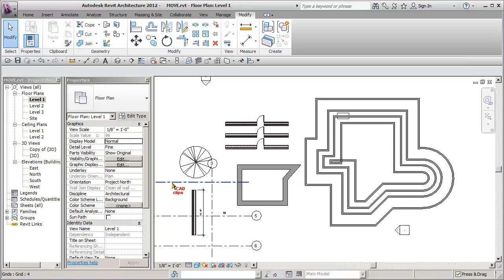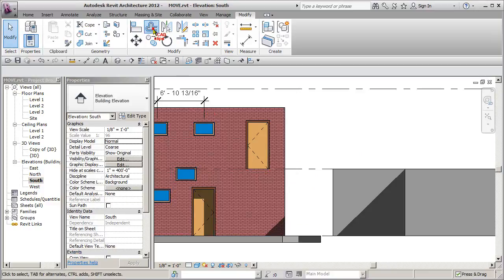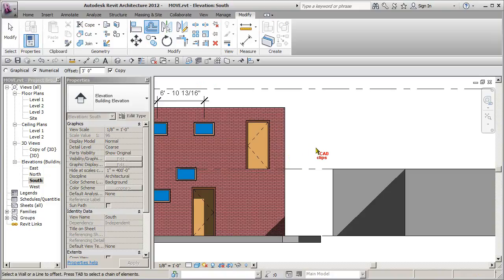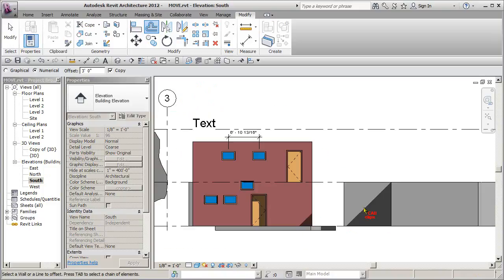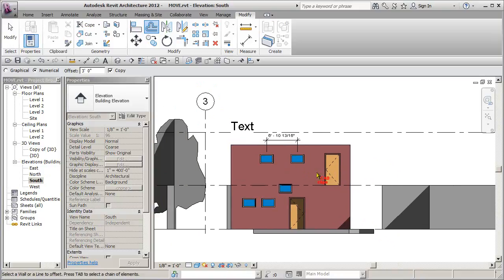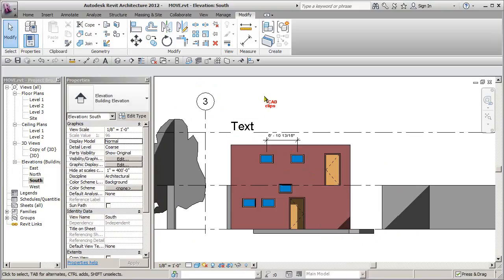Okay, doing offsetting in elevational views is a bit tricky if you're just using walls. If you're sketching and maybe doing an in-place family, it will work. But if you try to offset an object in elevation, you'll find most times you're going to get the stop sign. Nothing in here is really offsetable. There are objects you can use the offset with, but not with anything in this particular view. Mostly it's used in sketch mode and in plan view.